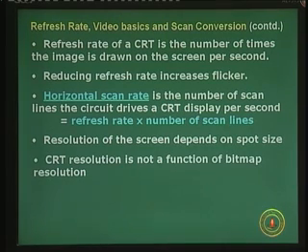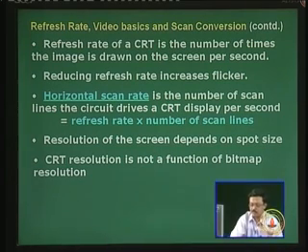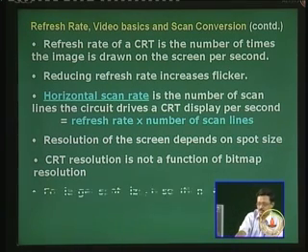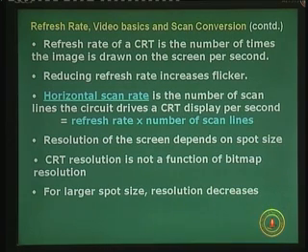CRT resolution is not a function of the bitmap resolution. I repeat, the spot size dictates the resolution, and the resolution is not a function of the bitmap resolution on the graphic system, but it is basically a function of the spot size. For a larger spot size you can have it, but resolution will be very poor. It's better to have a small spot size, but there are limits of manufacturing technology which cannot make the spot size smaller than a particular limit.